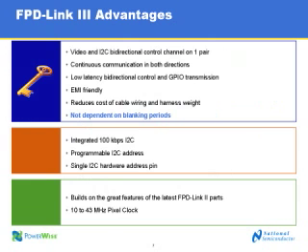It's EMI friendly so that people who are designing systems can meet the EMI requirements, and that's crucial for automotive applications. And finally, the upshot of being able to put all of these capabilities into one pair is that it reduces the cost and the weight of the cable harness, which is an important part of the systems. And I just want to emphasize, this technology is not dependent on blanking periods.